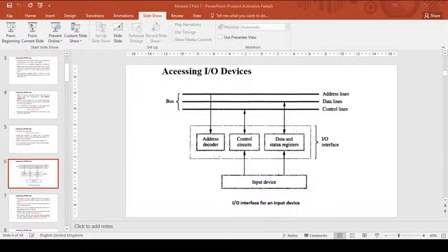Only then send the character from the processor register to the DATAOUT register. The SOUT flag is nothing but bit 1 of the status register, so indirectly you are checking SOUT by checking bit 1 of the status register.